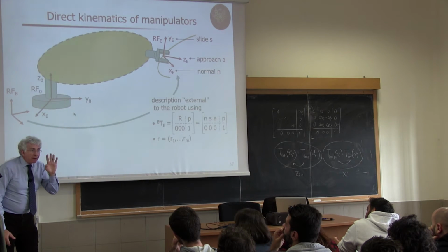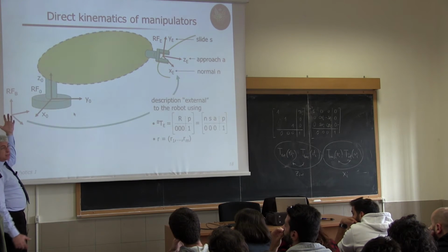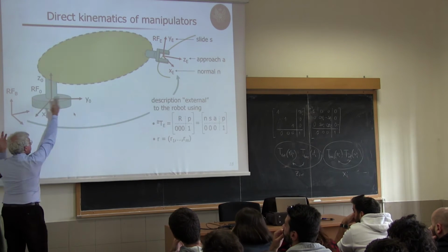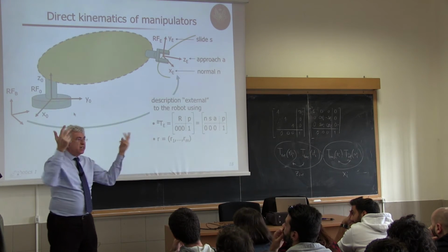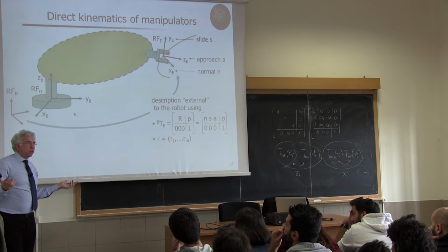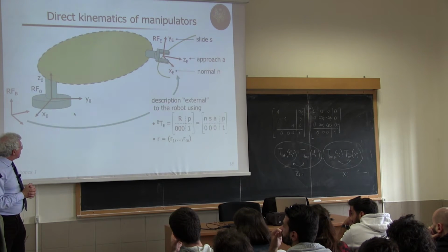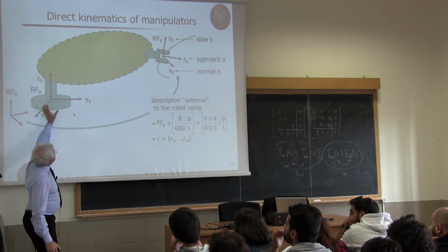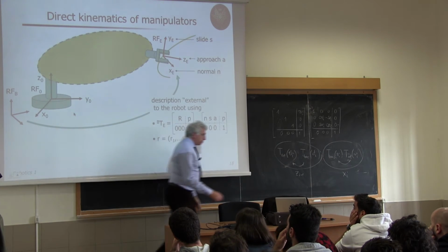And it has no Denavit-Hartenberg parameters, because this can be placed as I wish, and this is placed also as I wish. So there are 2 frames not linked in any sense, so I need the full transformation matrix to characterize the pose of one with respect to the other. Okay, then I have this frame, and then inside I have all those other Denavit-Hartenberg frames